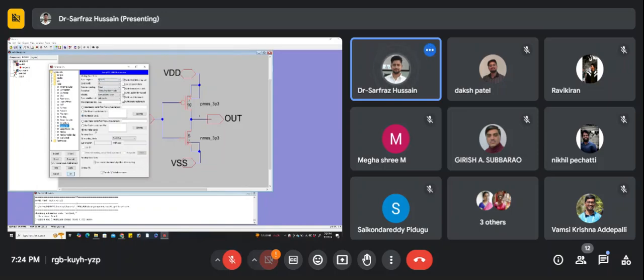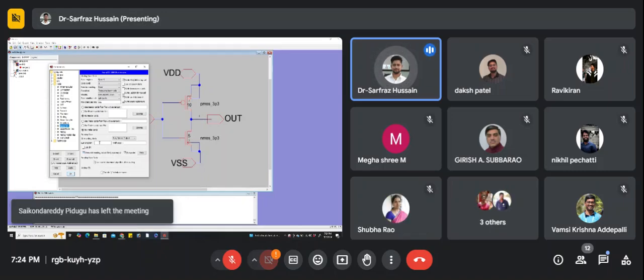After doing this, in the running spice section you have to select "run ignore output", because I'm running this simulation in Spice 3. For running the program, I have to give the location of LTspice here. Then select these two options, run probe and overwrite existing output file. Above this, we have to run the program, so that location we have to show here.